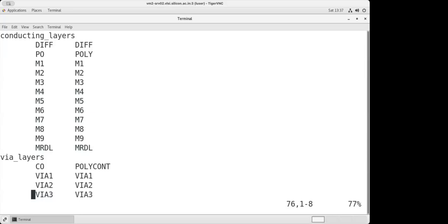There are a few foundries, they are saying, okay, I can understand metal one, metal two, not as M1 and M2. I understand this thing as CA, CB. So like GlobalFoundries, they don't have the concept of M1, M2, M3, M4. They have the concept of CA, CB, BA, BB, TA, TB. They define the layers in this particular way. So the ground level, maybe they will say it's a CA, then the next is the CB. There is a TA and the TB.